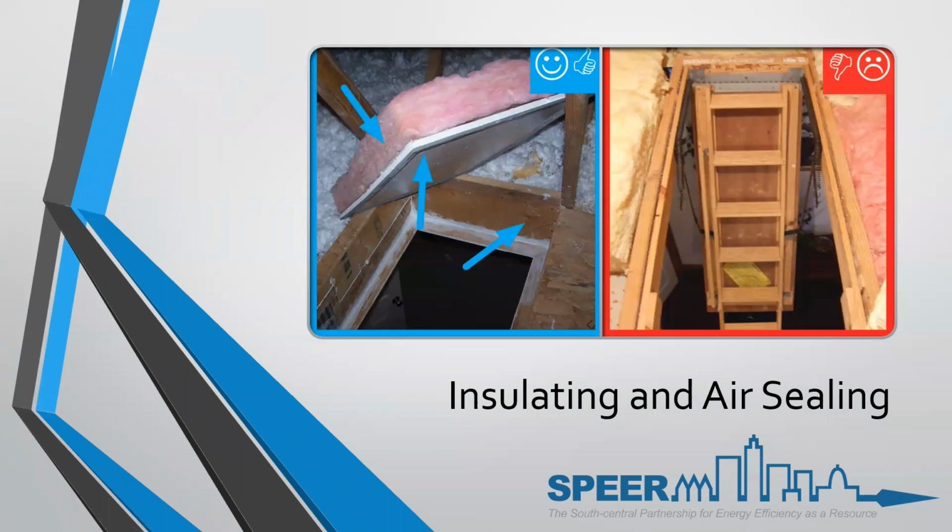We were just talking about that, but scuttle hole covers, vertical attic knee wall doors, and attic pull down stairs should be insulated, air sealed, and weather stripped. I'll say that with the caveat, if you read what the code says on scuttle hole covers, it's not part of this chart, but you can reference a different part of the book: vertical knee walls only need to meet the same equivalence of a basement wall in that climate zone. If you don't have a requirement, then it's not really required to be insulated.